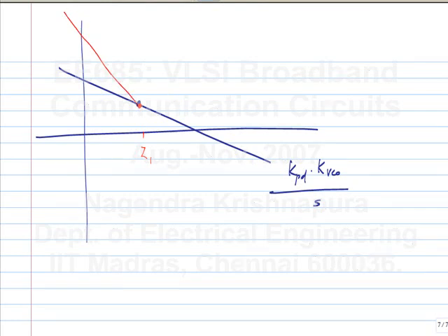We do this part because we know that this extra loop gain will give us a large lock range. We do this because it is a stable system. We need this for stability. And then let us say our omega ref is here. We need a large attenuation at omega ref. So we can of course continue along this, or we can even further attenuate those components by doing this. Okay.